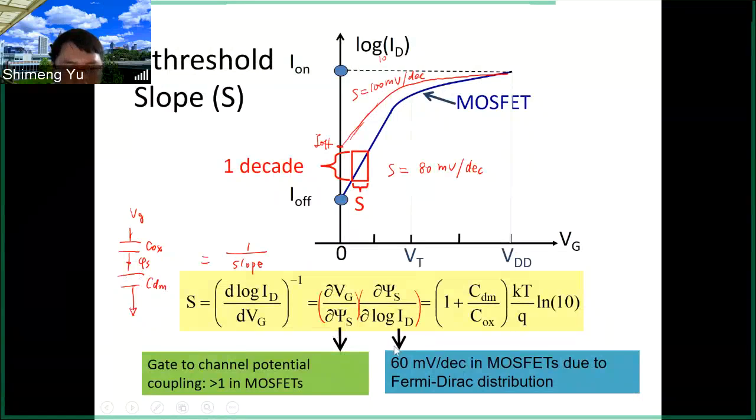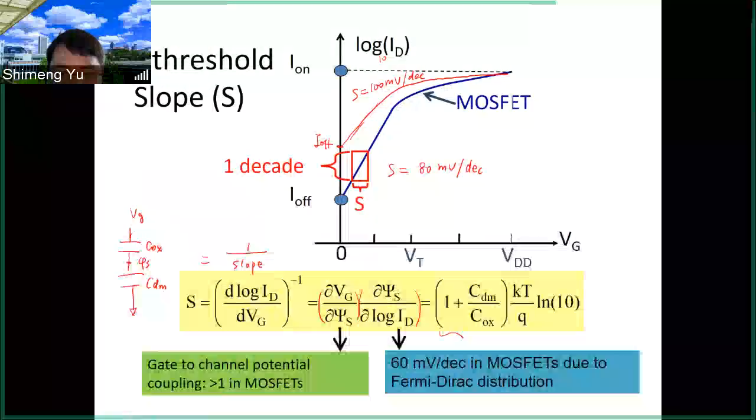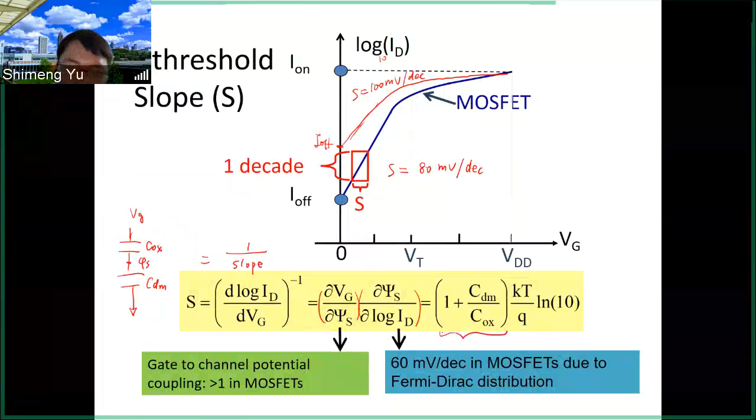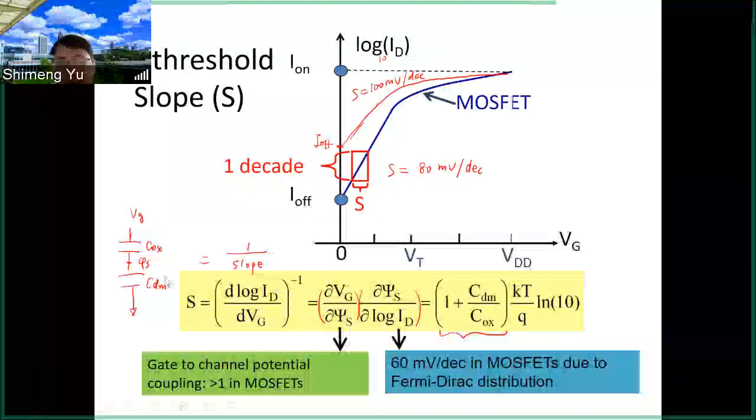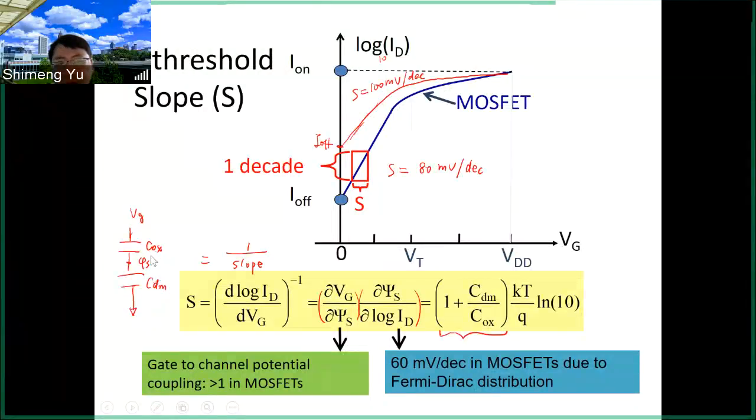And if you spell it out, it will be this one. So it's a voltage divider, and you use the voltage divider rule for capacitors. Capacitors are different from resistors: for capacitors in series, the 1 over capacitance should be added up.